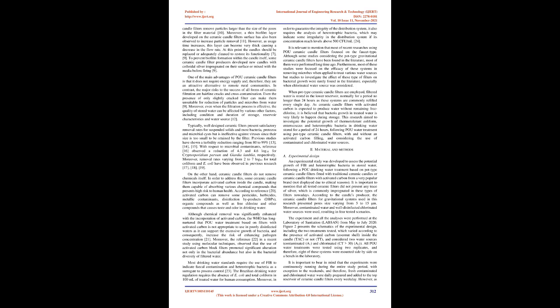When pot-type ceramic candle filters are employed, filtered water is stored in the lower reservoir, normally for a period no longer than 24 hours, as these systems are commonly refilled every single day. As ceramic candle filters with activated carbon are expected to produce water without remaining free chlorine, it is believed that bacterial growth in treated water is very likely to happen during storage.